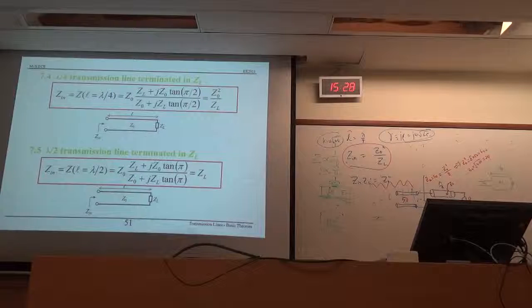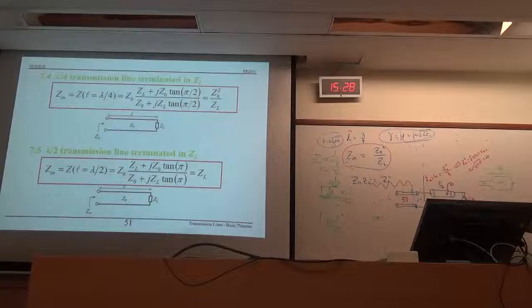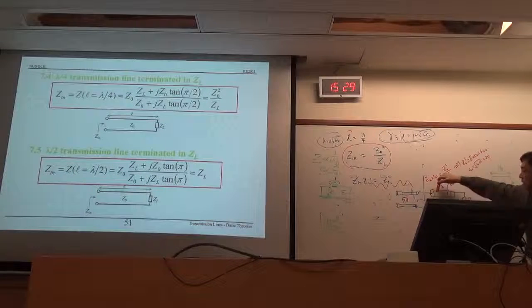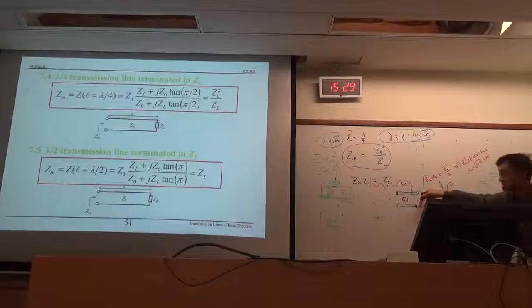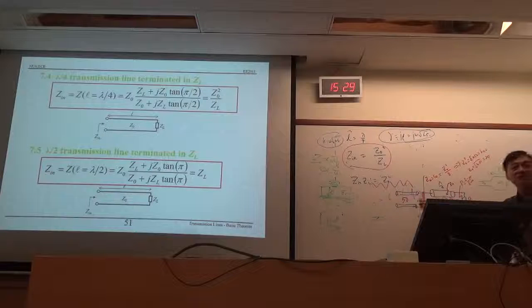So that means if I insert a 20 ohm characteristic impedance transmission line between this and this, and make it a quarter wavelength, the input impedance at this point will appear as 50, and now this is matched. There will be some standing wave from here, obviously, because at this point the reflection coefficient is equal to (8 minus 20) over (8 plus 20). So there is a standing wave, but it is limited between these sections only, within this small section, and will not disturb anything upstream.